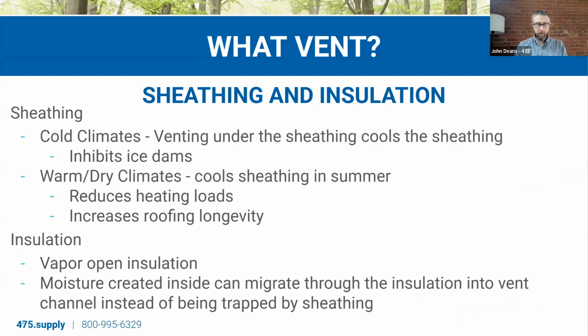So what are we venting? Specifically, we're ventilating the sheathing, we're ventilating the insulation. So the sheathing, particularly in cold climates, it cools the sheathing, and we can help avoid that ice dam effect that we were just talking about. In warmer, drier climates, it can help cool the sheathing in the summertime, which can reduce heating loads and increase roof longevity, which is pretty true for most climates.